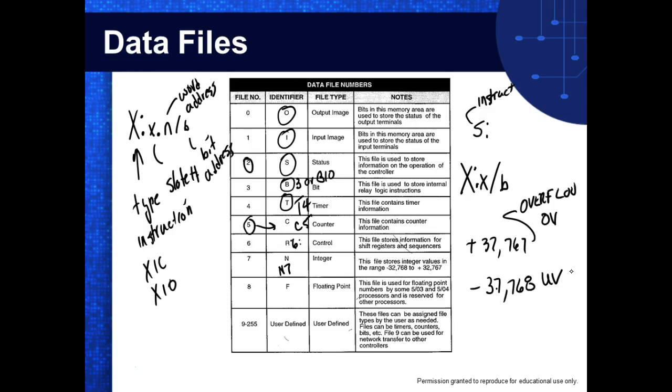You wouldn't know. But what we could do is constantly reset the first counter, right? So every time it got up, it would increment the next one and reset itself, and then start counting again. Then all I'd have to do to figure out my total count is take my second counter, whatever I use for it, as my multiplier, right? Does that make sense? And then multiply it by the first counter, and keep that in a floating point number, not an integer number. If I keep it in an integer number, I'm going to be limited to the signed numbers anyway.